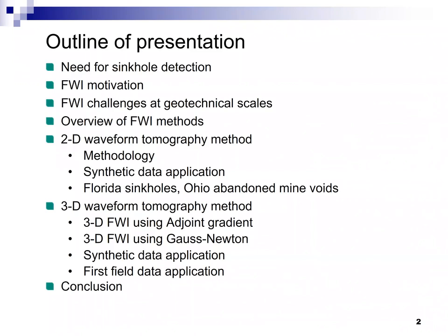So this is the outline of the presentation. I will talk about the need of the sinkhole detection a little bit, the full waveform inversion motivation and challenges at geotechnical scales. A quick overview of the full waveform inversion methods. I will talk about 2D and 3D full waveform inversion methods. For 2D, we'll talk about the methodology, synthetic data application and real data application for a sinkhole in Florida and an abandoned mine void in Ohio. And for 3D full waveform inversion, we developed two different methods using adjoint gradients and Gauss-Newton methods. We'll have a synthetic data application using both methods and compare the results. I will also talk about the first field data application using the two developed methods and compare the result with the invasive test, in this case, SPT. And then I will finish the presentation with the conclusion.